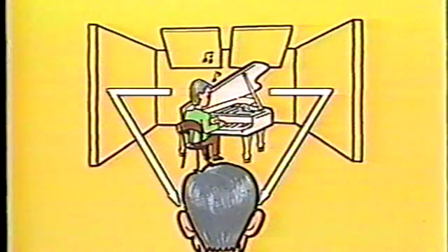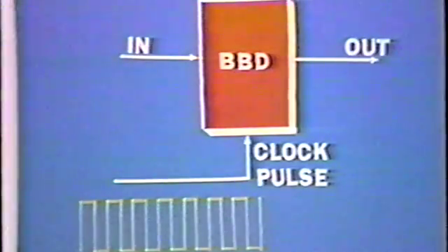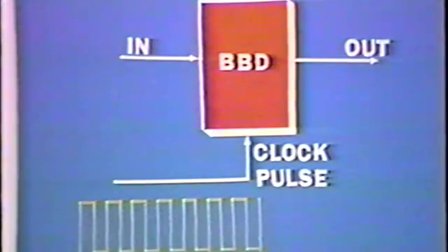With S1 off, the melody signals enter the stereo chorus circuit. With the Casio tone, almost all of the stereo effect is created using a delay element called a bucket brigade device, or BBD. The BBD stereo effect does not produce a clear position for the sound, but, by delaying the signals, the sound can be reverberated to produce the stereophonic effect. Sound signals can be delayed when they pass through the BBD. The delay time is determined by the clock pulse frequency.